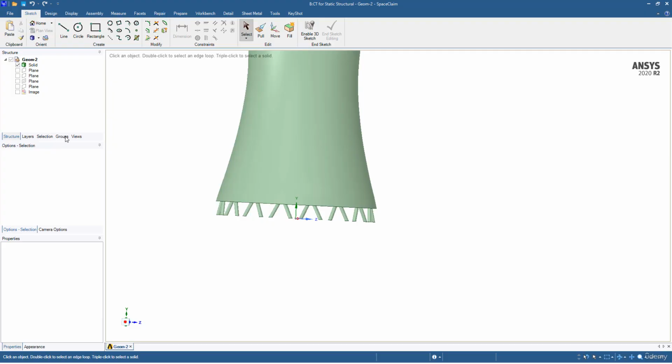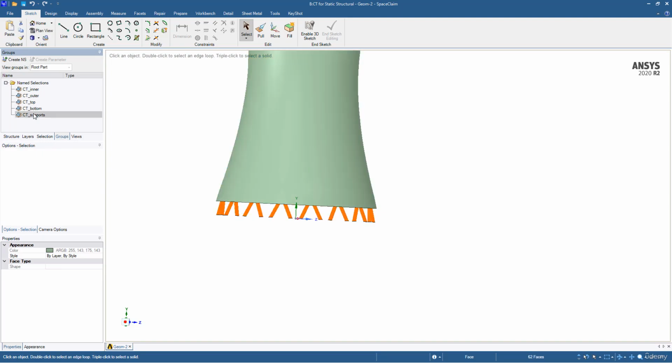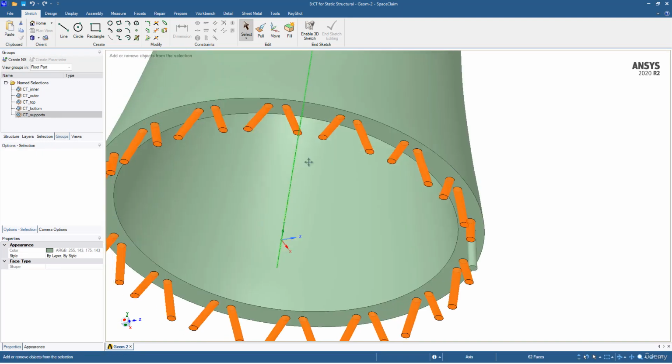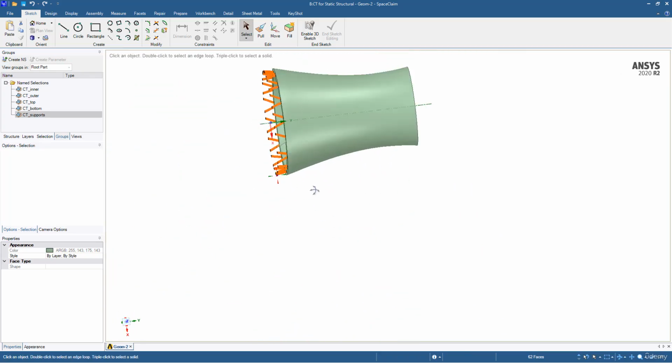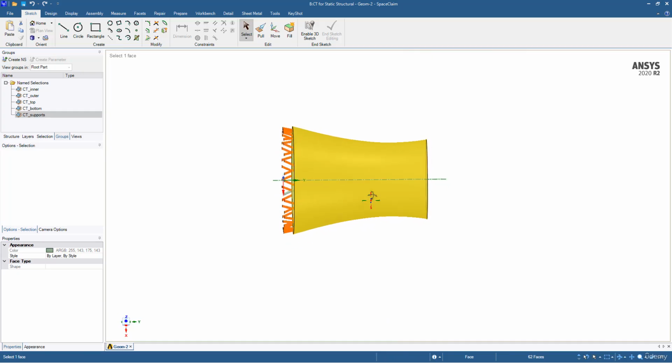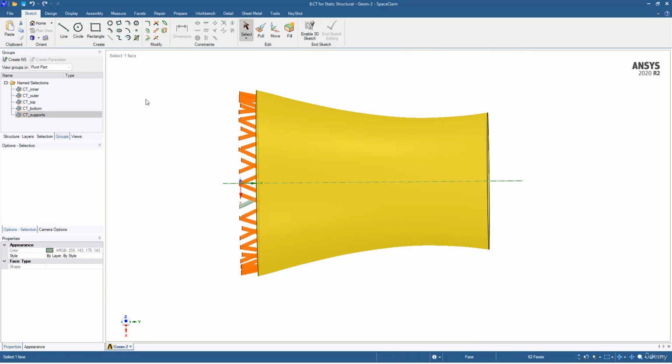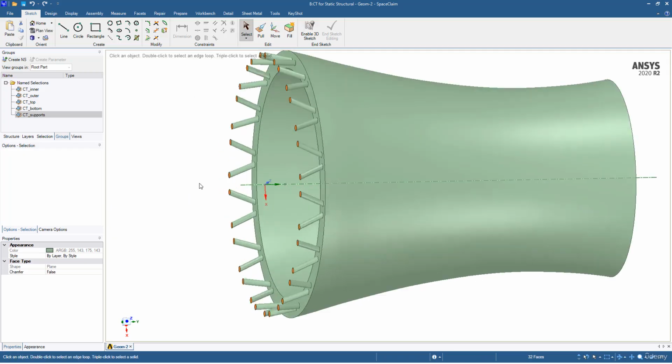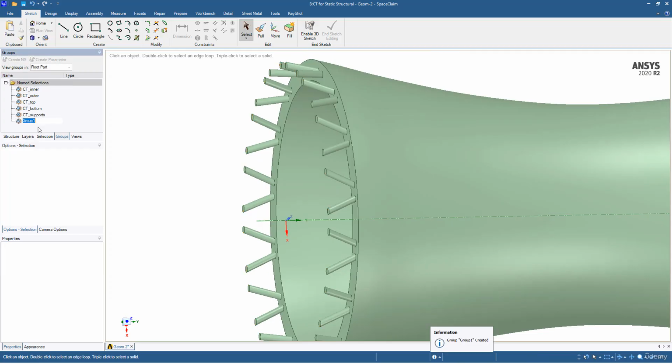Okay, geometry is open inside the static structural, so I just wanted to confirm these boundary conditions. And also on the bottom side, we have to provide the boundary conditions as supports. Because this part will be exposed, that means this will be the part of the FEA simulation. So we'll choose these surfaces, and I put it as the cooling tower fixed support.